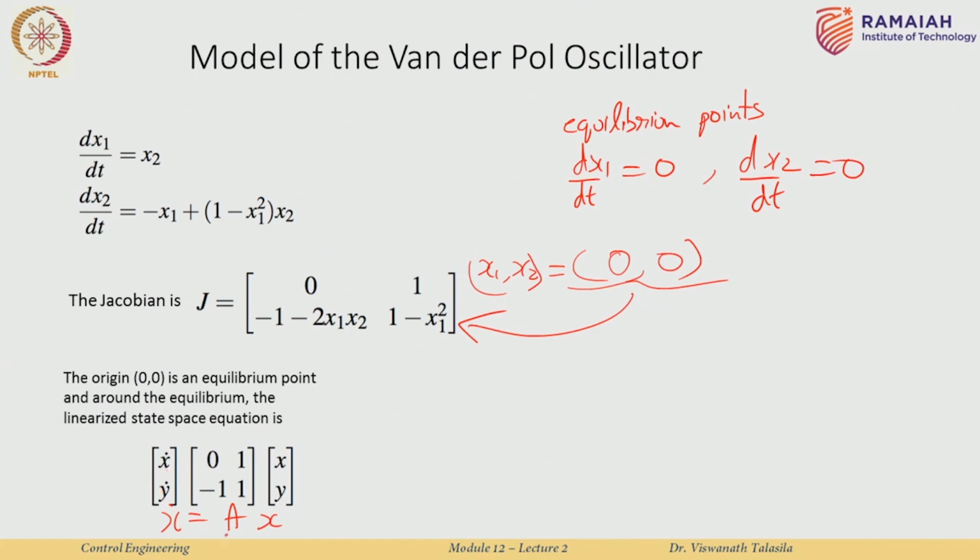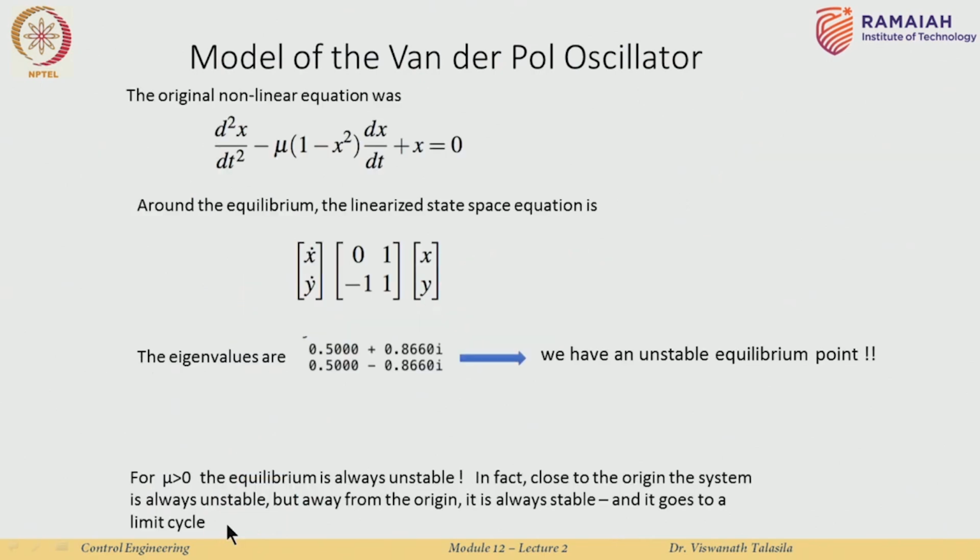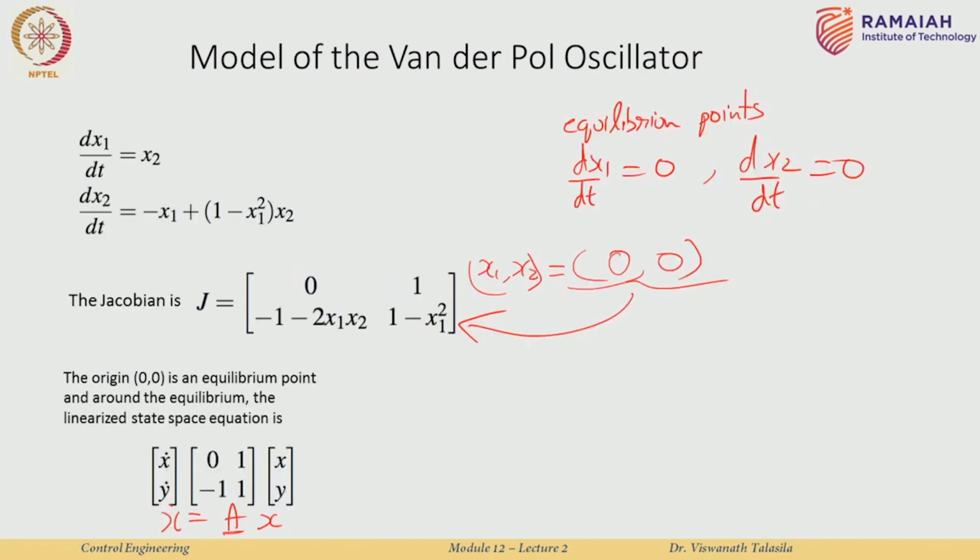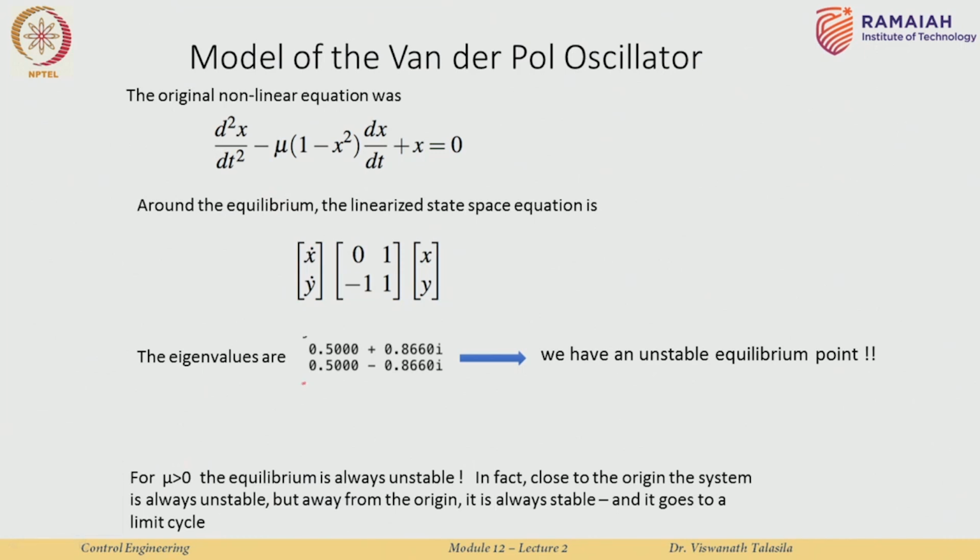Okay. So, now let us analyze the properties of this system. And the way we are going to do that is to again, as we always do, compute the eigenvalues. Remember in transfer functions how we used to compute the poles, that is really the first step you would always do. So, similarly compute the eigenvalues of the system, and you will see that the eigenvalues are over here. Okay. So, if you look at the S plane or the pole-zero map, you will find that the eigenvalues are over here.